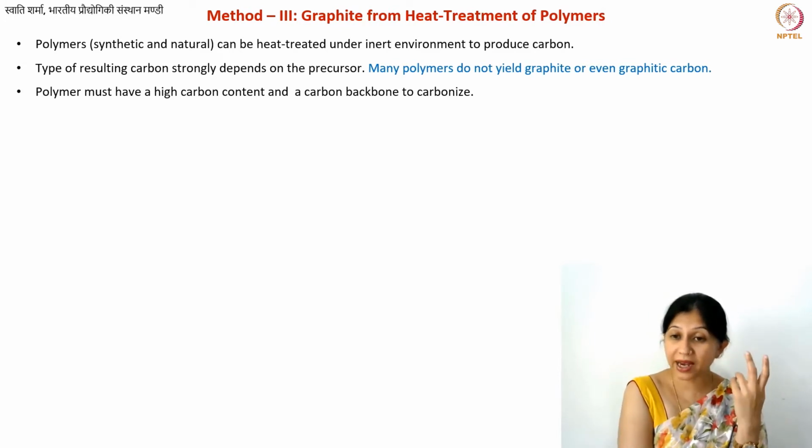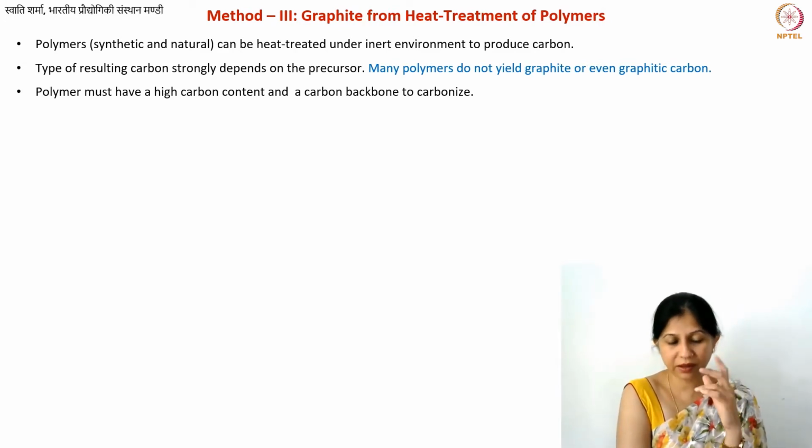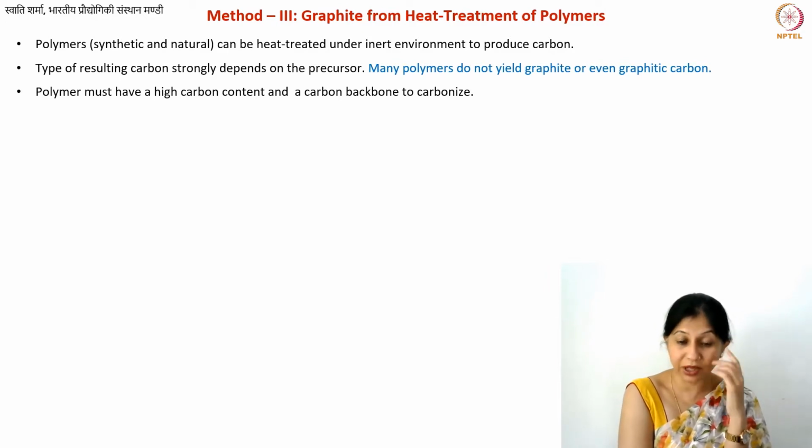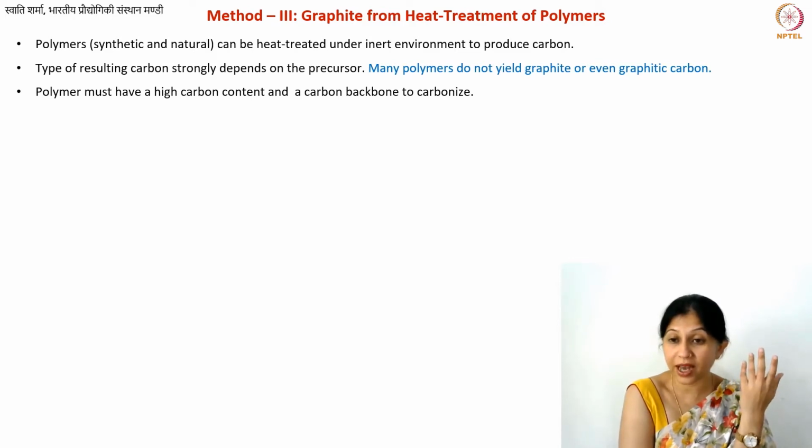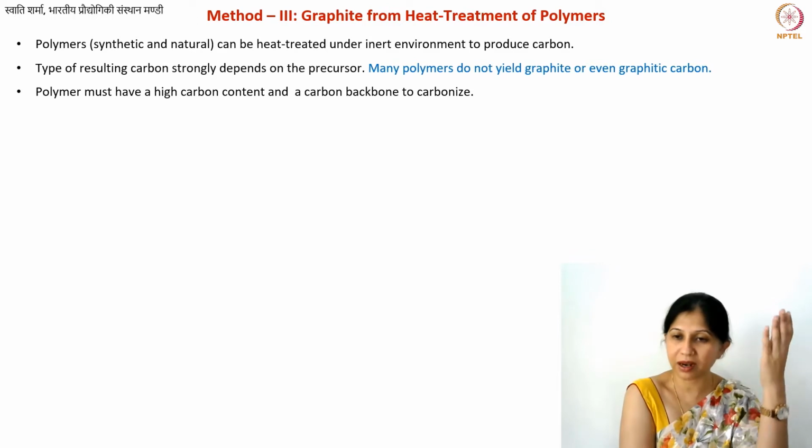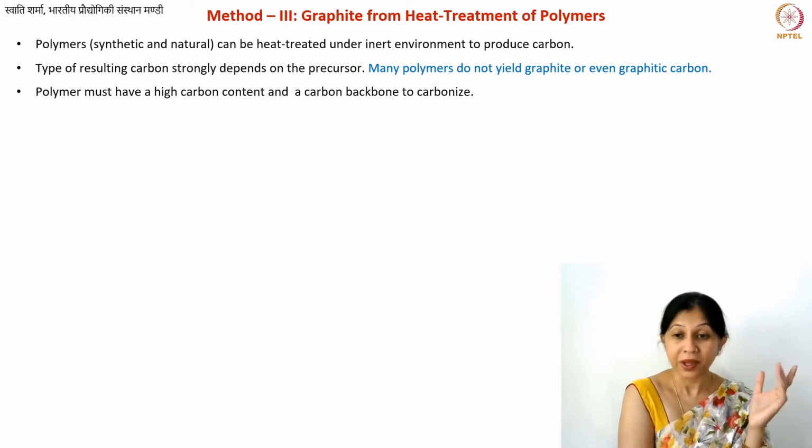If you have that, aromatic means you already have these 6-membered rings, but of course, when it's a polymer, you have hydrogen, it's CH. And what you want is to get rid of all of the hydrogen, and of course all other elements as well. Then, since it was in the ring-like geometry, you will get these graphitic regions. But graphitic does not mean it is graphite.